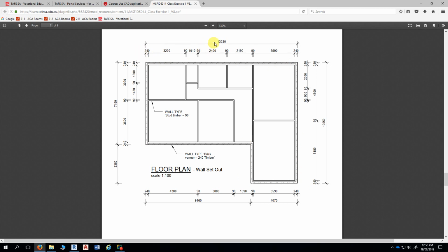So just note the approximate size of the building, so that when you're actually drawing your walls, you don't have to be exact, but you have to be close. So we're going to draw the external walls and generate this shape that's going to be fairly close to the actual size, but not exact. And we're going to draw in a clockwise direction.